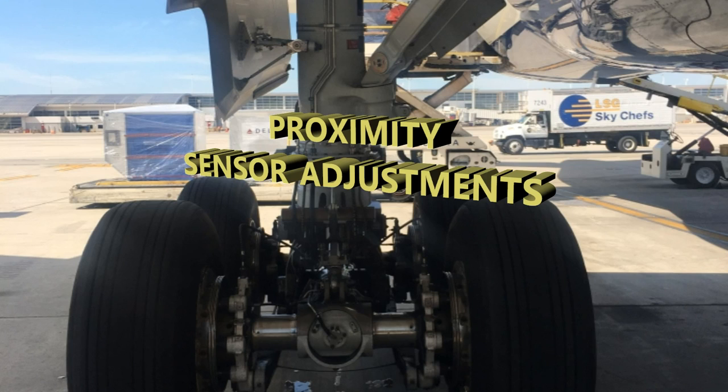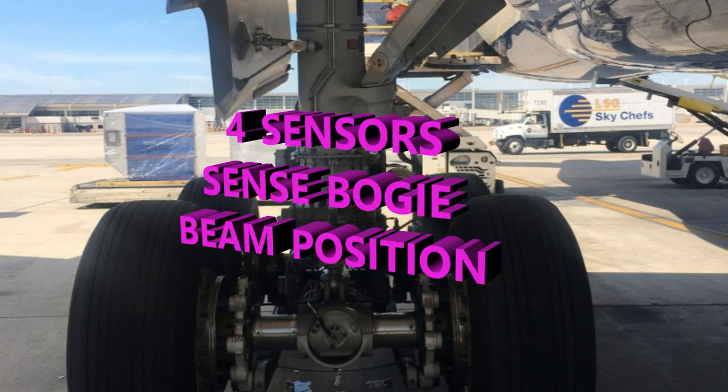Okay. All right, so let's go back to the monitoring. I talked about the sensors at each location, and then you also have the bogey beam position, so you need data on that, and then there are 4 sensors related to that. So 4 sensors are going to be sensing the position of the bogey beam, and they're going to be sending the data to the LGCISs. And they're going to be measuring the movement between the target on the bogey beam and the sensor on the sliding tube. So those are the 2 components.